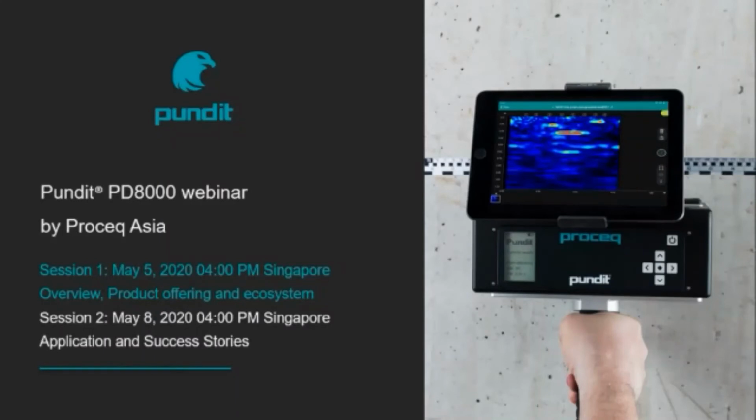And another question from Indradi, the last question. What is the minimum distance between the rebars that we can detect to identify each individual? I would like to answer this question. So next webinar, we will open some application notes, especially for PDA1000. There's a real case study, which is 2 rebars at a shallow distance overlapping. So we can see the two rebars very clearly. I'd like to say this test method in some situations can be better than GPR for this kind of rebar detection.